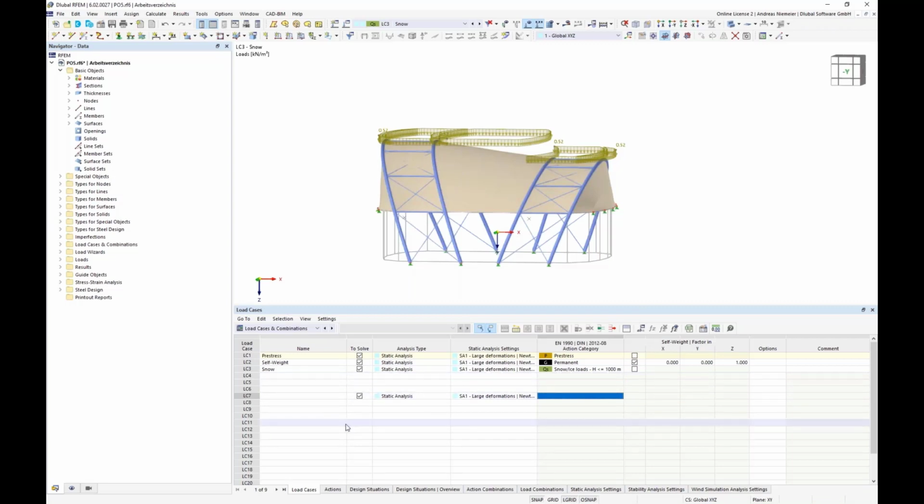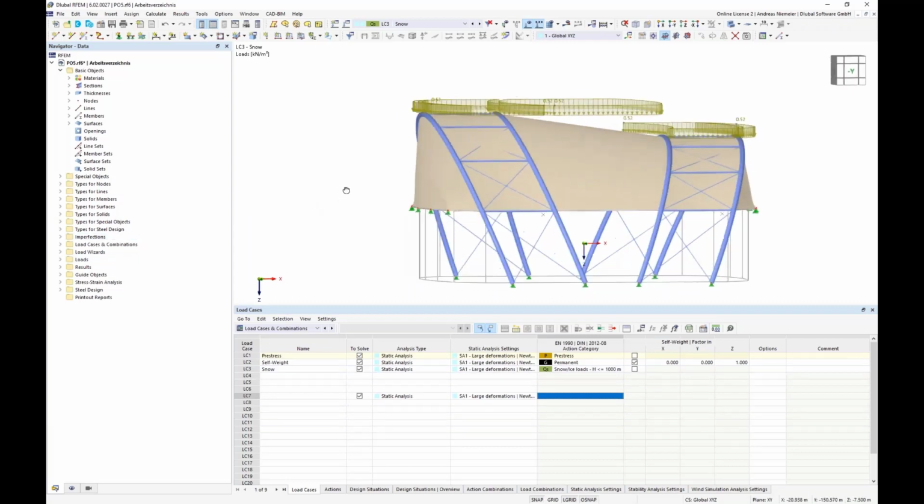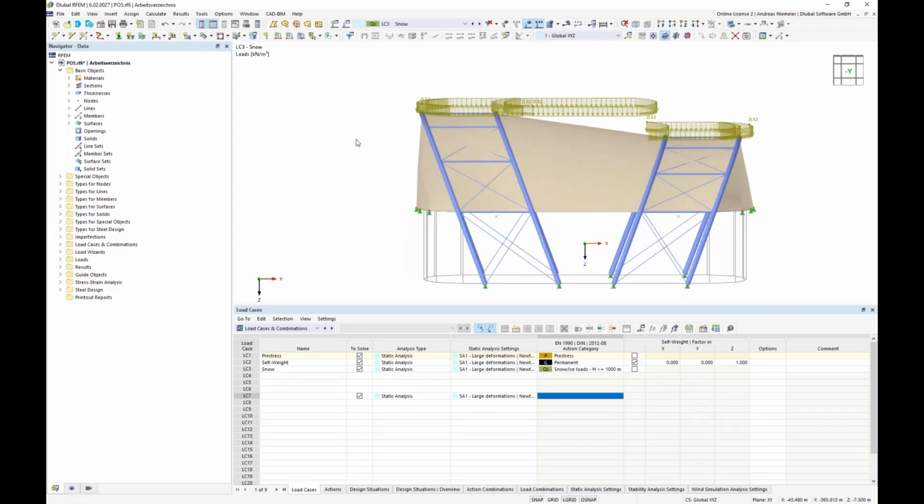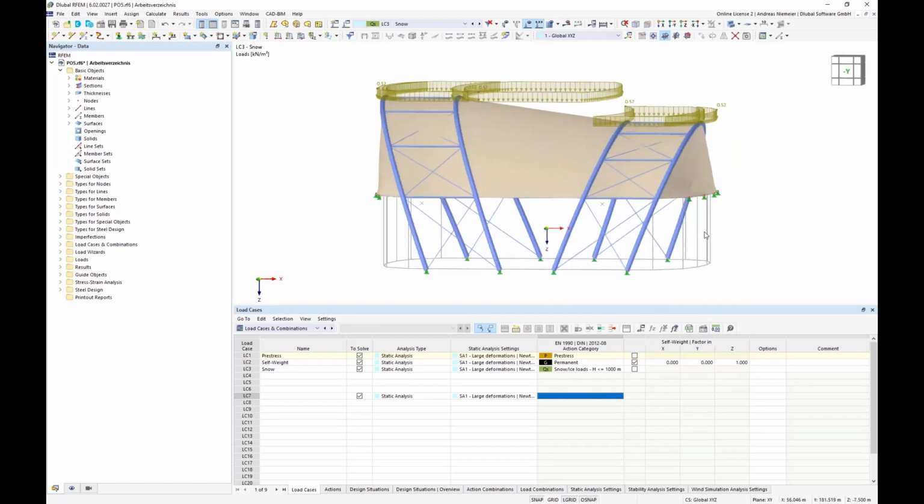But if you place this model into a wind tunnel, you have to know that the wind can maybe press here again, but it can also flow downwards and upwards. And this is not real, because here we have a building below. So if you do wind tunnel analysis, you have to give the program a model that fits to this. And therefore we have to model also these walls inside.